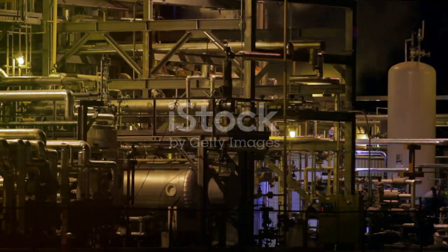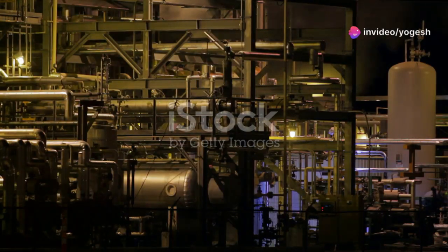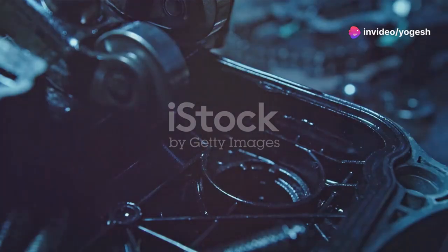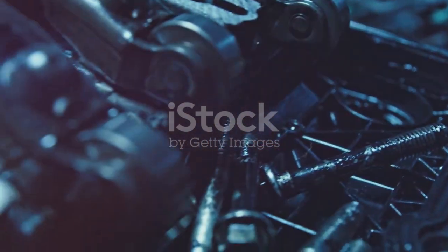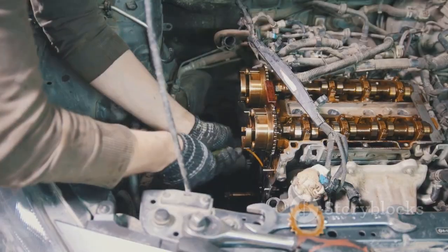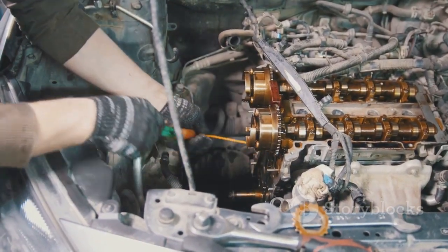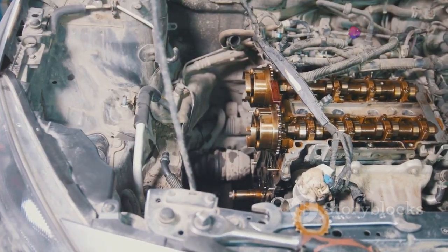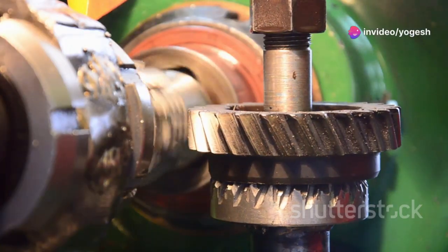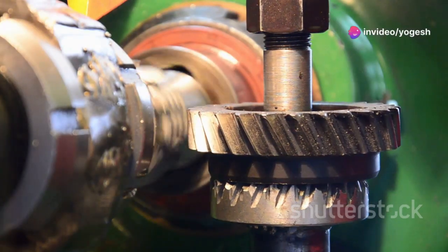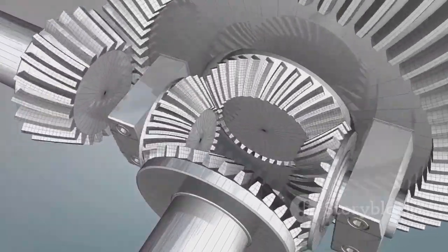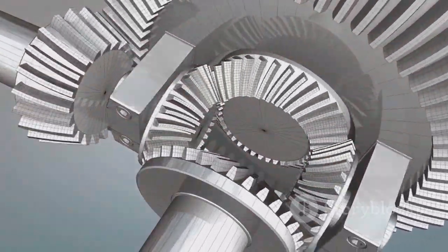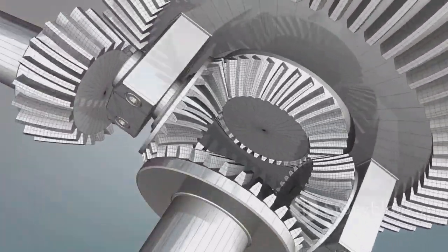Auxiliary views aren't just theory. They're used to build real-world marvels. Take a cam in an engine. Its precise profile controls timing and performance. Standard views can't show its true shape, but an auxiliary view does, allowing for perfect machining. Or a bevel gear. Its teeth are complex, changing shape along their length. Only an auxiliary view, projected along the gear's axis, defines the tooth profile for smooth operation.